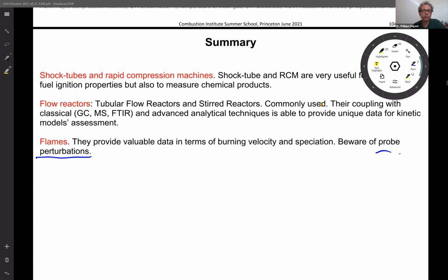Well, I cannot go into this type of detail, but if you look at Progress in Energy and Combustion Science, a paper by Egolfopoulos and co-workers, there is information, and also they give you a reference to some original papers where it is described. In a premixed flame produced by a Bunsen type burner, which temperature measurement technique provides the most accurate value for temperature measurements? Well, probably the best technique is optical, and it can be done through LIF.